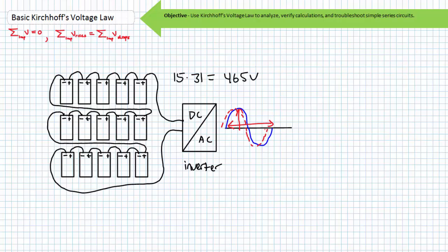A quick note about these series aiding configurations before we continue though. Let's say one of those 96 batteries in the Chevy Volt suddenly loses a connection, or one of the neighborhood kids tosses a large opaque frisbee onto your roof, and it perfectly covers up one of the solar panels. Trust me, it's a really big rectangular shaped frisbee. All the other solar panels are exposed to sunlight and ready to rock, except the one panel in the dark. Let's keep it simple and say this darkened panel's resistance increases to infinity, or becomes an open circuit condition and current through it ceases. What happens to the current in the whole series string?